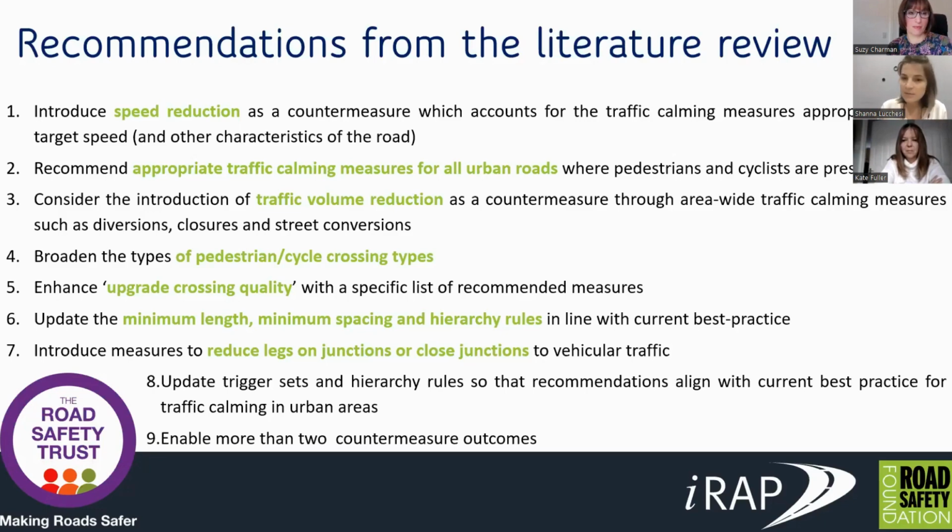An example of a minimum lane rule is that additional lanes, such as overtaking lanes, must be required for a minimum of 1 kilometer before they are considered viable to the SHRIP. In the case of minimum spacing rules, a good example is grade separated pedestrian crossings, which must be at least 1 kilometer, that is 10 consecutive 100-meter road segments, apart. Because if we did not have this rule, the model may recommend this countermeasure every 100 meters, which will not be feasible for any environment.